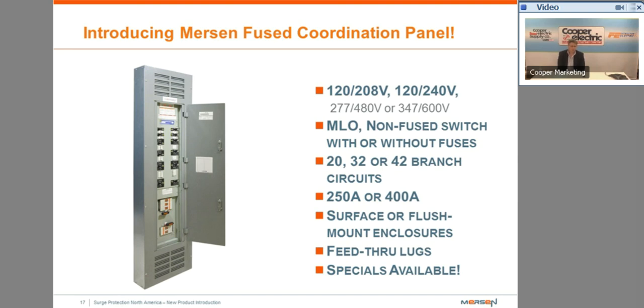So it's really using the best of both worlds, which is use the circuit breaker for overload protection for its convenience and resettability, and using the fuse for the short circuit protection. By doing this, it allows us to only require 3 different ampere ratings on the fuses to fill this panel. And again, it is a Square D panel that we buy out and supply with our fuse holders and fuses.